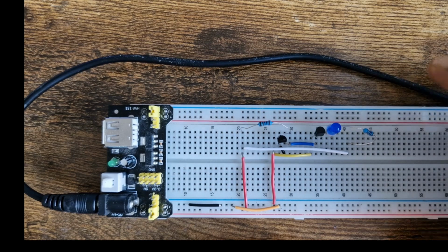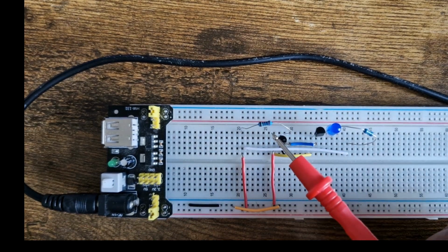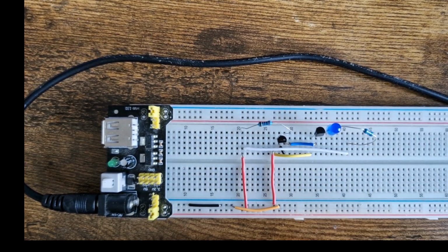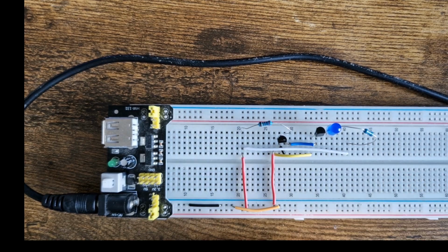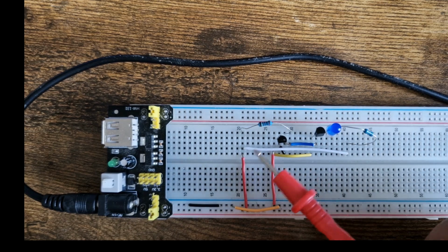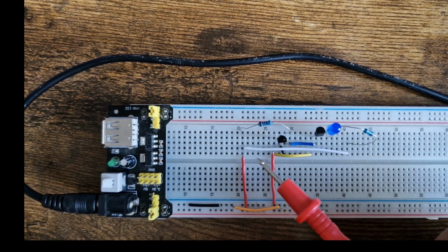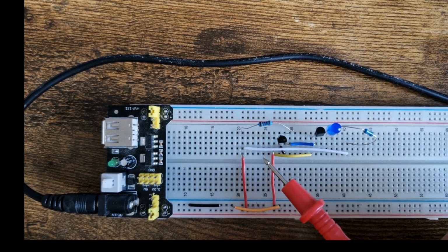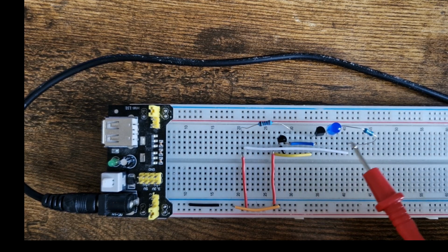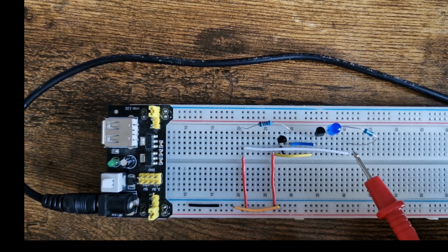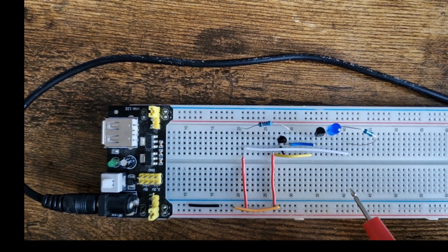Okay, so what is to be seen here: the value of this resistor is 2 kilo ohm, and the value of this resistance is 100 ohm actually. We will now measure the current that is being generated by this part of the circuit, and then we will measure the current that is being mirrored into this part of the circuit. Both should be identical to each other, and that's exactly what we look for.